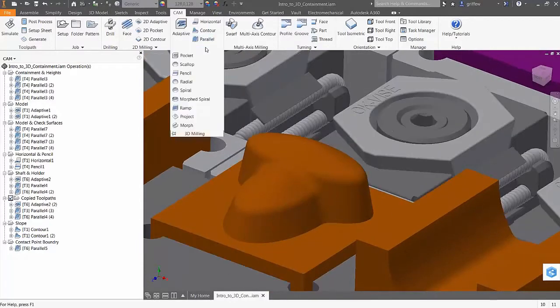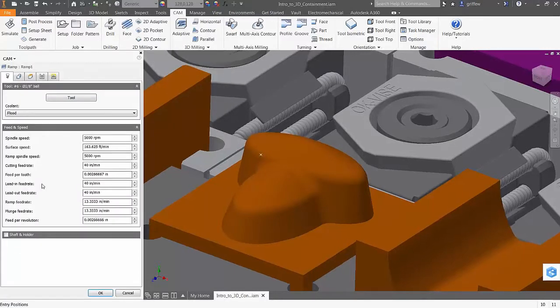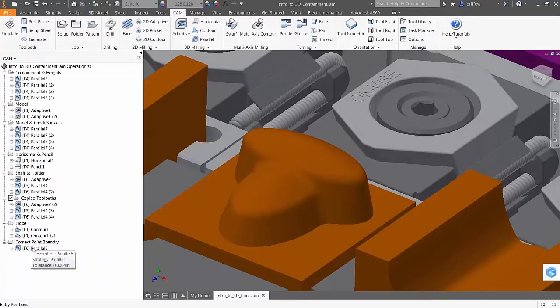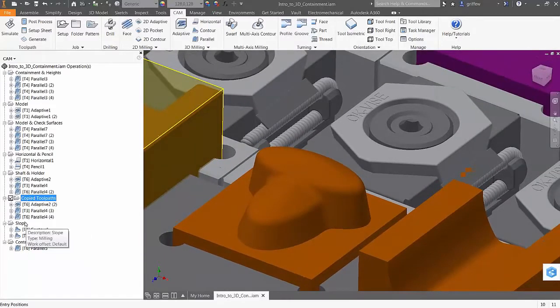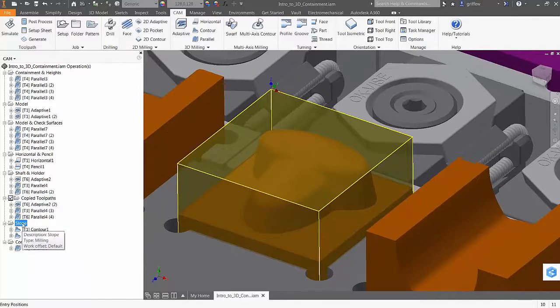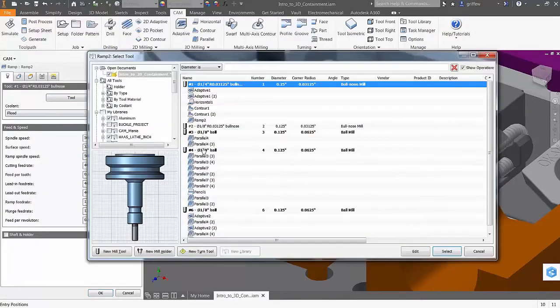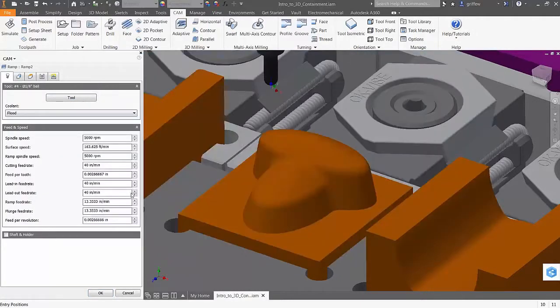So when you work with a ramp toolpath, if I look at a ramp at one here, and I'm going to look at this part, make sure I'm in this default. If I would have done that, it would have been in the left default toolpath. So I want to make sure I go into slope. I'm going to hit Shift D. That makes it my default. So now when I add a toolpath, it's going to be in that default. It's going to look at that part. So I'm going to choose a ball nose end mill.